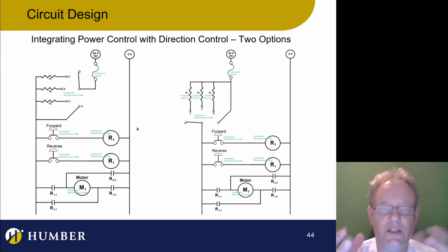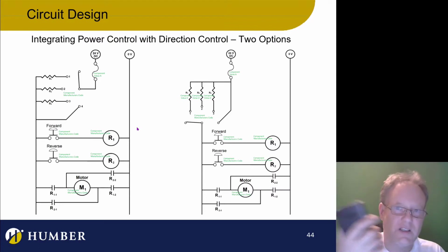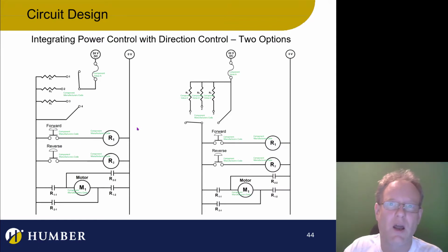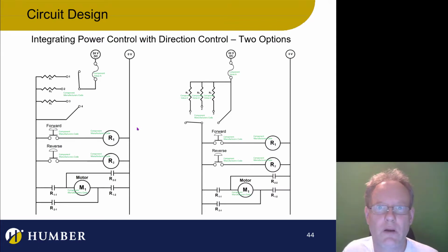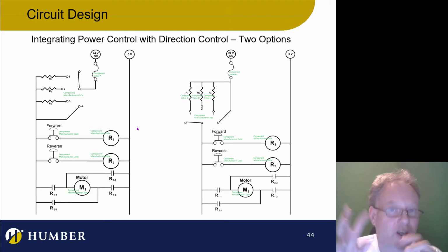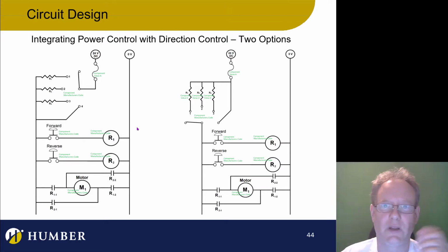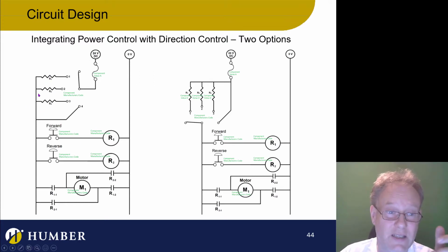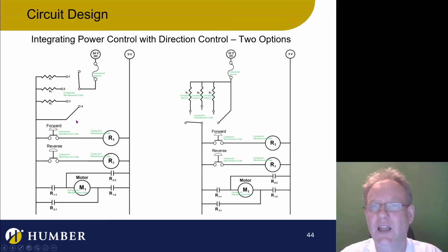You fully understand that the power of a motor is not just that you pull it off the shelf, it's a 100-watt motor, let's turn it on and we'll have 100 watts of power. No, that's not what's going on. It's dependent on so many different factors. And we can see that the controlling of the power is not a linear relationship. There are a couple different ways to do it, and pulse width modulation is the most common, although we're not dealing with integrated circuits.